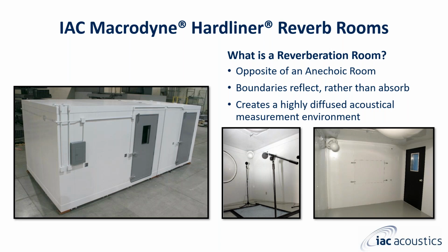The achievement of the required room ambient sound levels, sound absorption coefficients, appropriate reverberation times, and correct volumetric ratios between room and test object requires the necessary acoustical experience and know-how. Contrary to rectangular designs used today, it was once believed that skewing of the walls and ceilings was necessary for reverberation rooms to achieve a diffused field. However, excellent results are being obtained with rectangular construction.